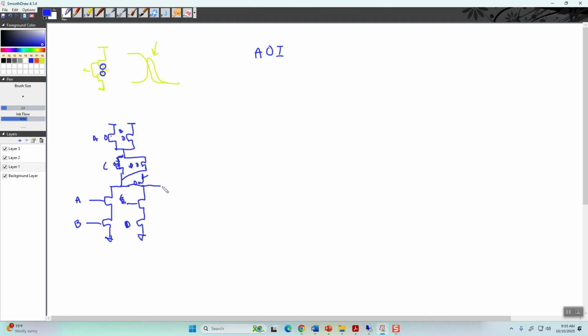Okay. So now, when you're designing one of these gates, you need to know its capacitance, right? So what you do is you assume the worst case, so that if B is switching off and on, well, A has to be high, and then C is high, and D is low.